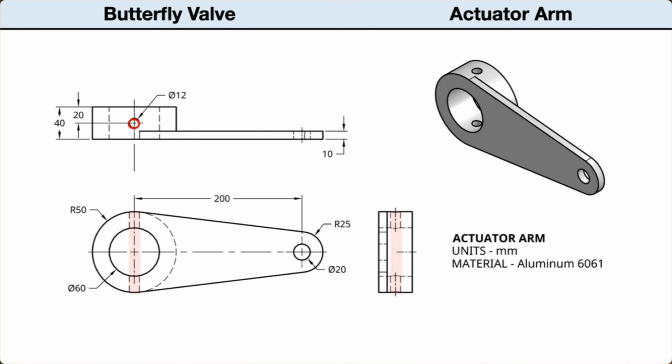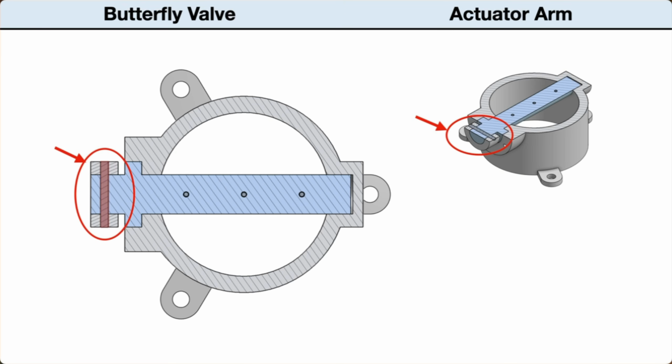Now looking back at the drawing, notice that there is a hole through the arm. The purpose of the hole is to receive a pin to lock the arm to the stem. This is a 12 millimeters through hole. The hole is centered on the large end of the arm at 20 millimeters. Also note, there is a matching hole in the stem to also receive the pin. We can add this hole to both parts now.